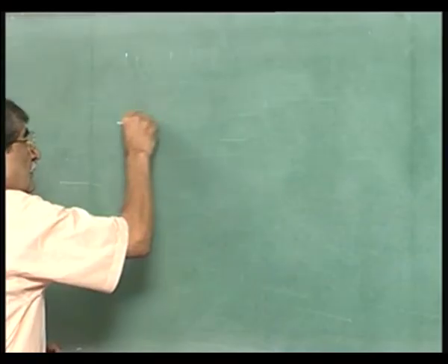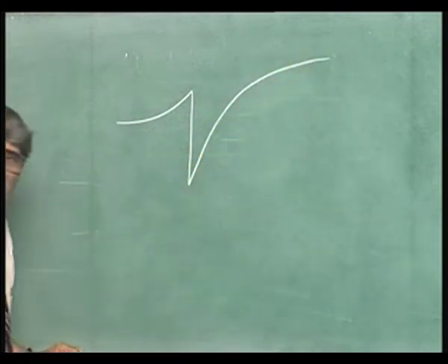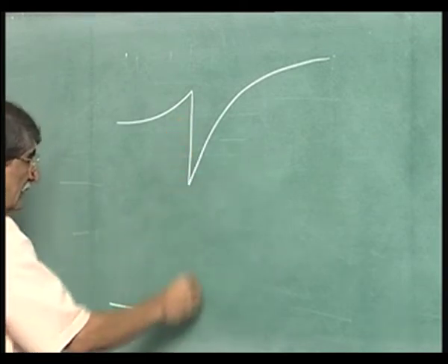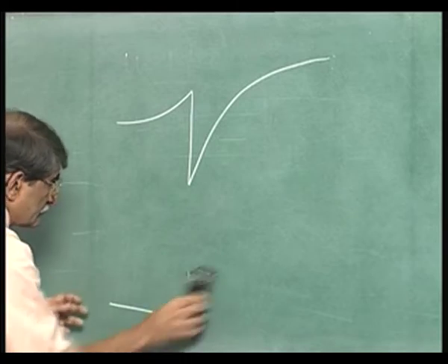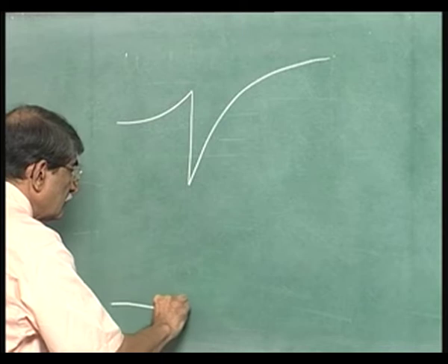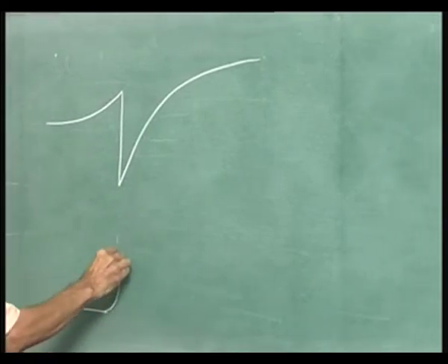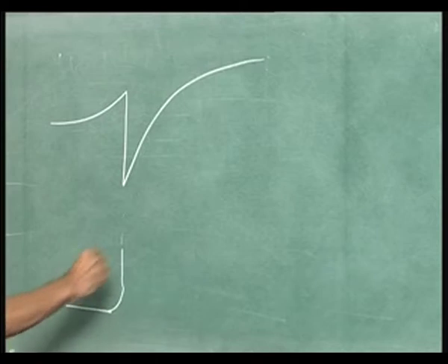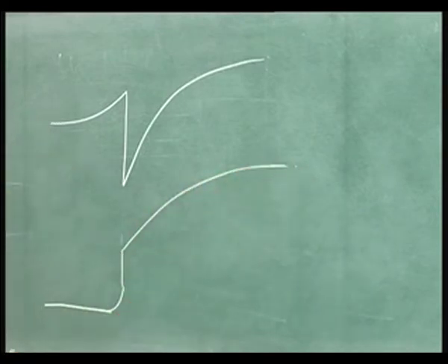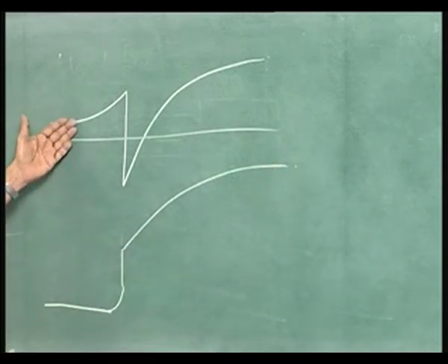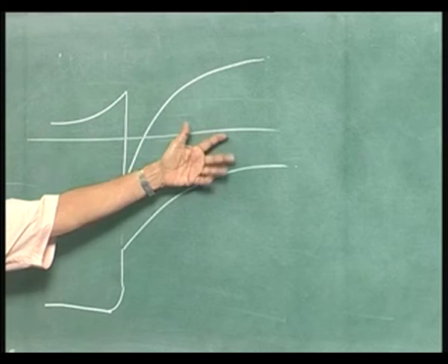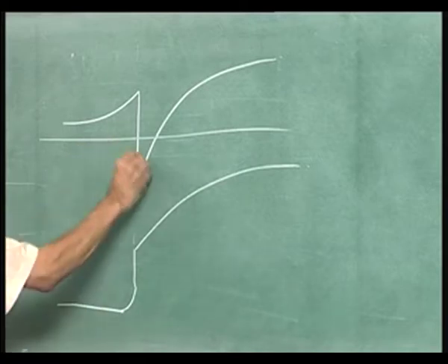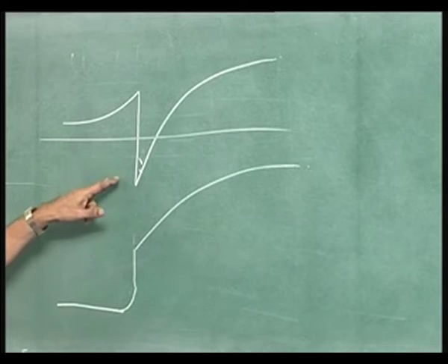See, that is the conduction band. You do not have to draw the vacuum level now. And then parallel to that, up there, discontinuity there. I am not explaining how we went about that, because we spent quite a bit of time explaining that. That is the one. Now, you will have the Fermi level there. N type close to intrinsic, P type, Fermi level can be there. In fact, it will be there, because below the Fermi level electrons will be occupied. Electrons will be there below the Fermi level. This notch will hold the electrons.